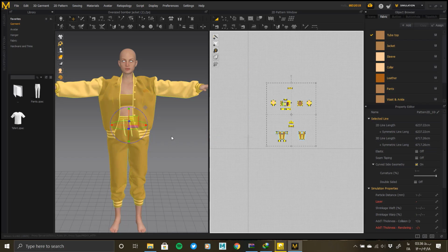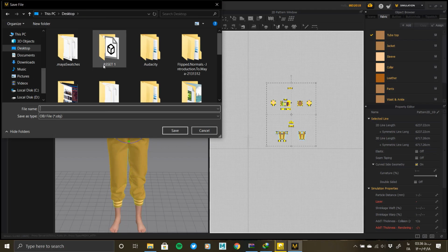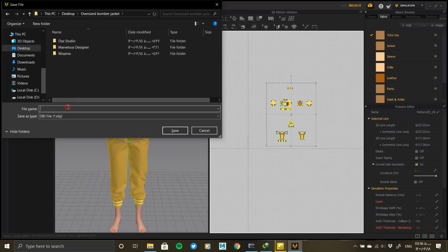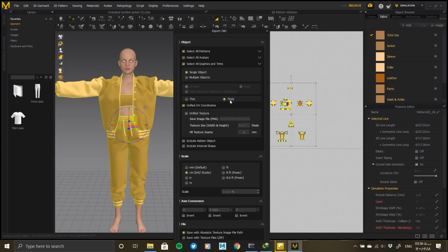Save the output as OBJ without characters. Select the single object mode, and choose one of the three modes, thin weld, thin unweld, and thick, based on our needs. Thick mode in thick parts, its UV is not defined. So in the case of thick output, it is better to define UV thickness separately, for other parts in that software.